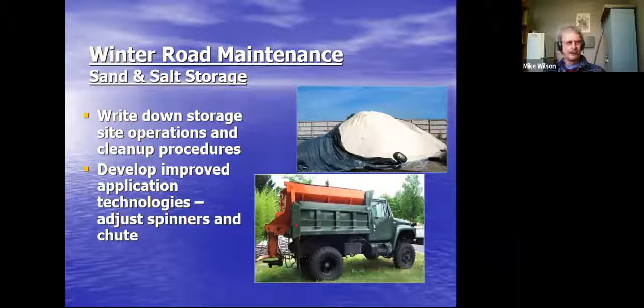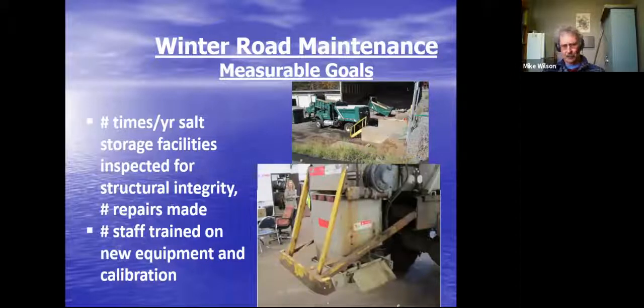You also want to develop improved application technologies in terms of salt and de-icing agents. Adjust your spinners, adjust your chutes, make sure they're calibrated correctly. You want to use some caution with some of this material. We're finding out that brine is more and more dangerous than we actually think it is.